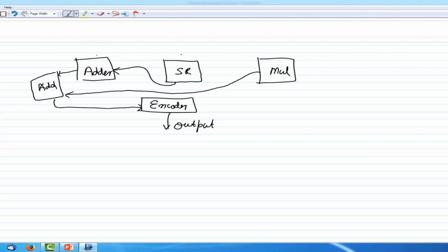So it is possible that the SR latch takes 1 nanosecond, the adder takes 1.6 nanoseconds, the multiplier takes 2.9 nanoseconds. So if you look at this adder, the first input is ready at t plus 2.6 nanoseconds, and the other one is ready at 2.9. And finally, some data then again comes out. So managing the timing of all of this would be very difficult. So what do we do?